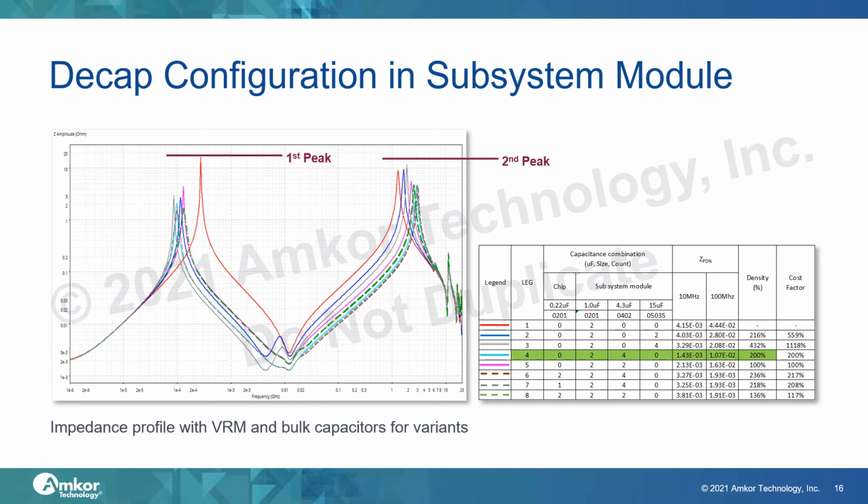This shows that using a larger capacitance to suppress the impedance peak is not an effective way, and larger is not always better, especially if mounted and spreading inductance are extremely low.